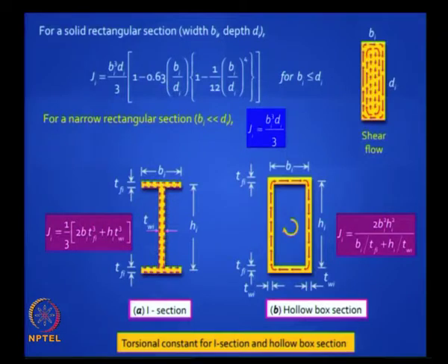It's like a circular section, so it's very effective against torsion. Okay, that's because it's closed. If you cut that box anywhere and make a slit, then it's not as effective, and if you have a slit you can go back and use the formula for a narrow rectangular section and add up for the different segments. Anyway, these formulas are available if you want to use them in practice.